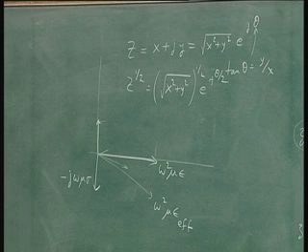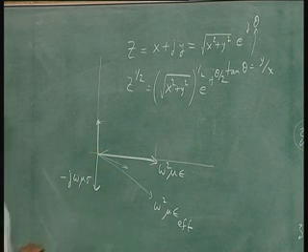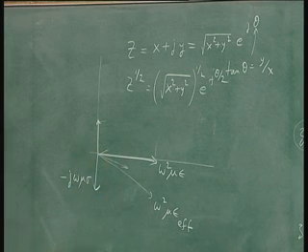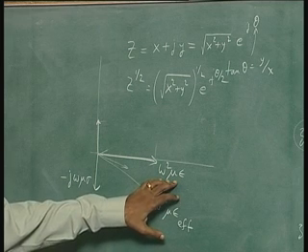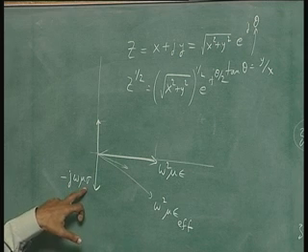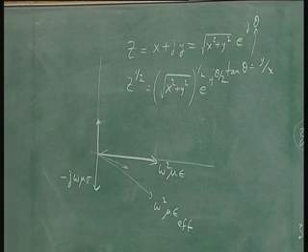But if, for example, in skin depth where you have very little omega squared mu epsilon, then you can't really take square root of omega squared mu epsilon as the dominant part of your real part. In fact, it will be the other part, the j omega mu sigma, that will dominate even the real part of the solution. So, this is an approximation.